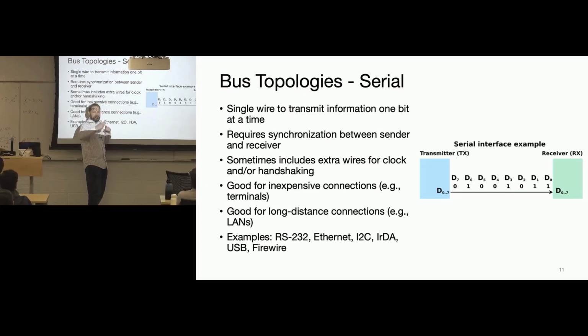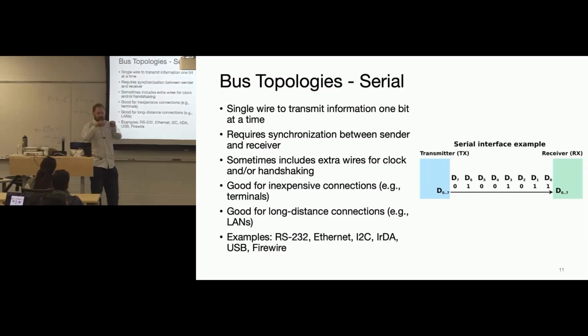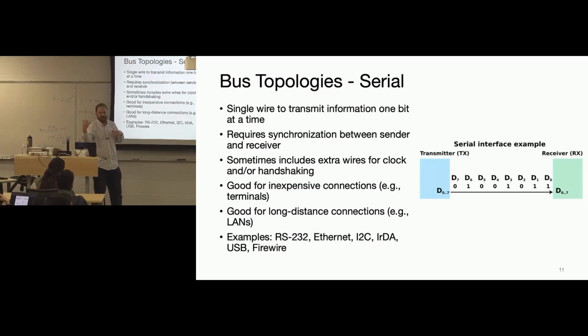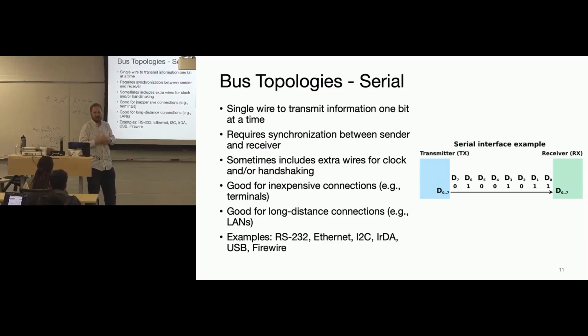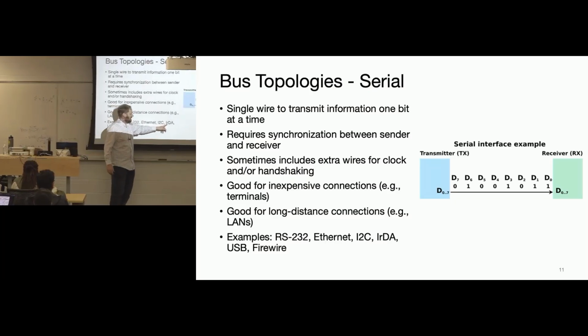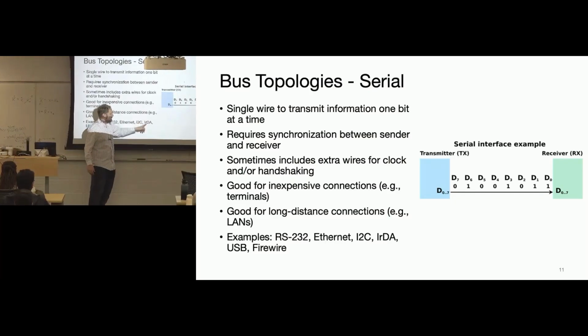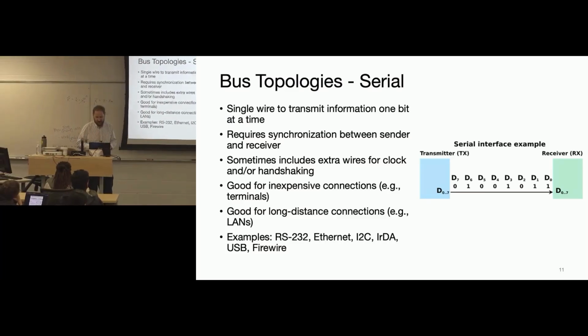But it's just one signal, blinking on and off. You can't really get parallel. Then you'd have to have different wavelengths, and the receiver would have to have multiple wavelength detectors, and it would be painful. So your microcontroller will just treat it like a serial interface. It just happens to be converted to terahertz instead of megahertz.